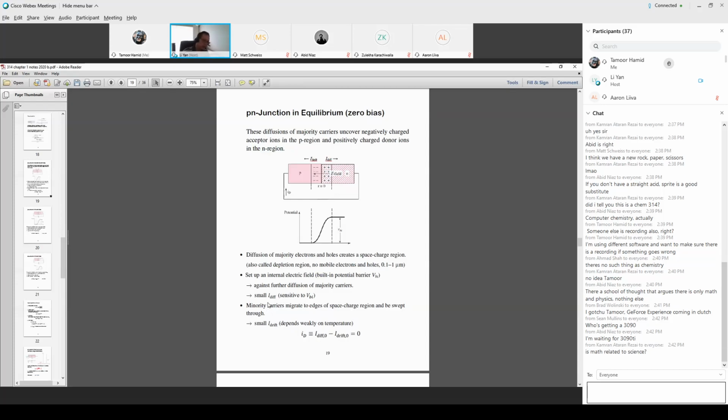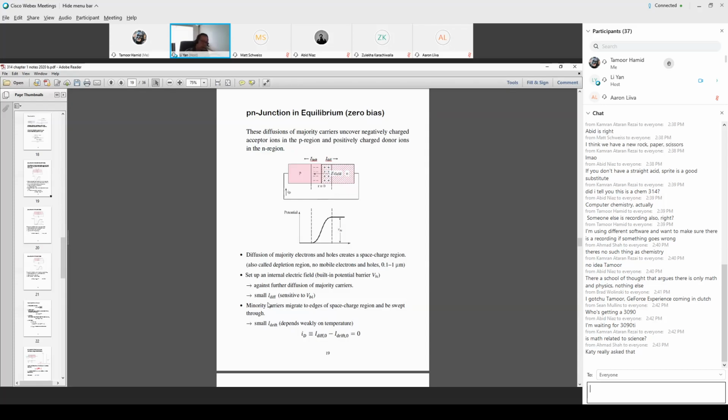It's a little bit of a chicken and egg, but here you have the distinction. What's first? You need initial diffusion to create the potential barrier. But once you create the potential barrier, diffusion of these electrons will be difficult. But these minority carrier electrons can get through.